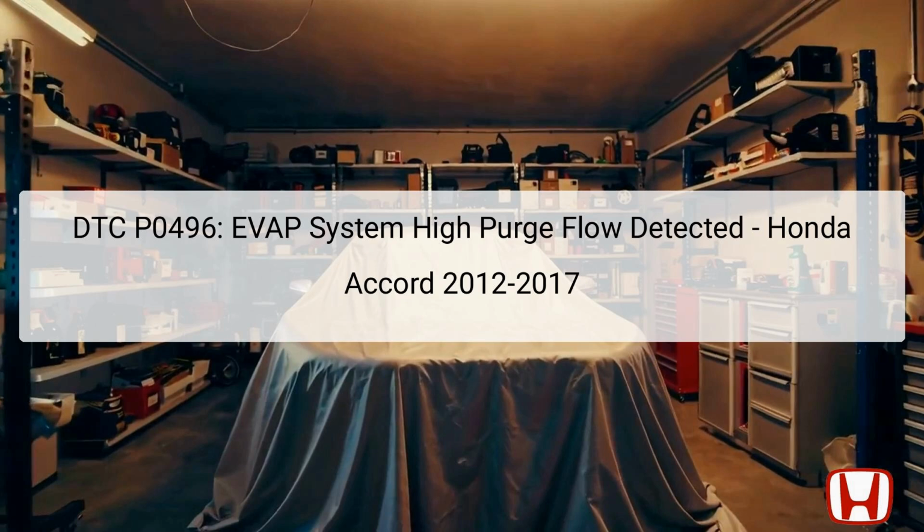The components directly involved in this malfunction typically include the EVAP canister purge valve, the EVAP canister vent shut valve, and the fuel tank pressure (FTP) sensor, located in the fuel tank area or near the EVAP canister. An abnormal purge flow can cause increases in emissions and can also lead to issues with vehicle performance and fuel efficiency. Identifying this error is crucial for maintaining compliance with emissions regulations and ensuring optimal engine operation.